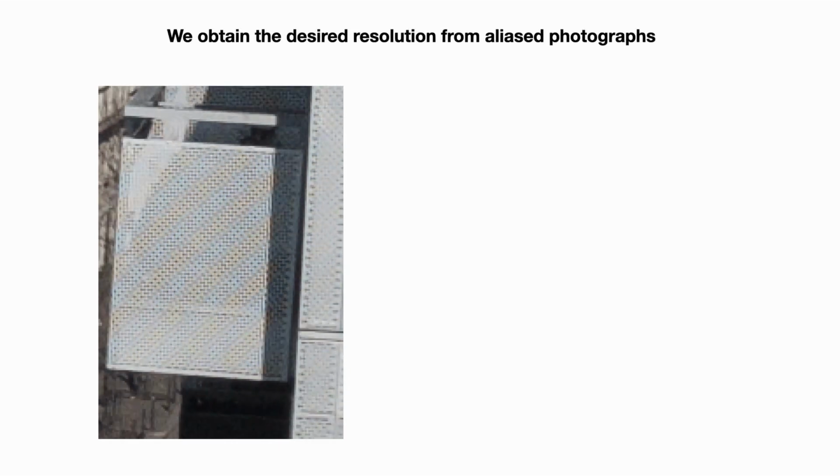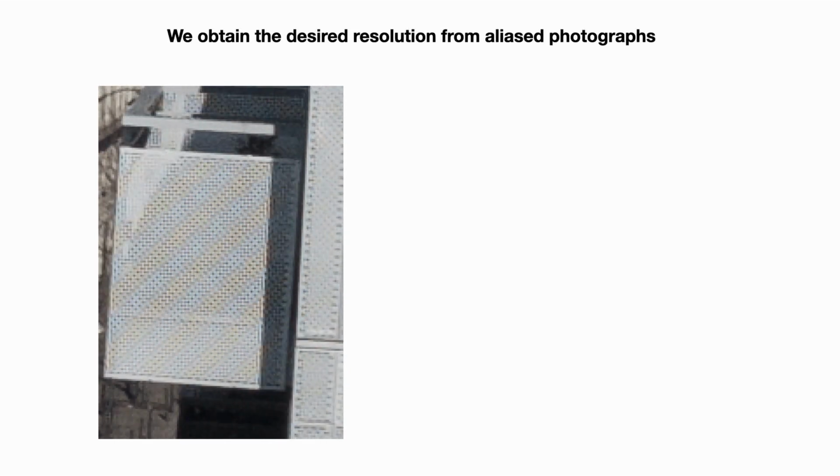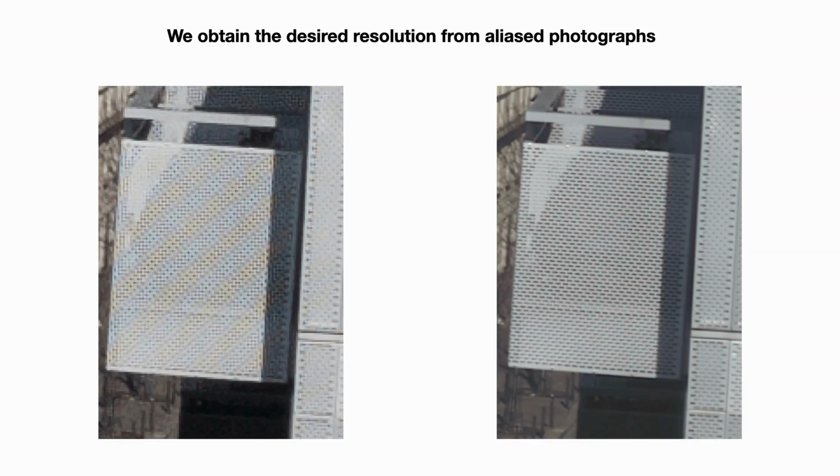An efficient way to improve the resolution of the image is to leverage aliasing. High-frequency details above the resolution of the sensor will result in low-frequency artifacts in the low-resolution frames. For instance, notice the varying colored artifacts on the metallic grid across various frames caused by hand tremor. These artifacts from several frames can be used to successfully reconstruct the high-frequency image on the right.